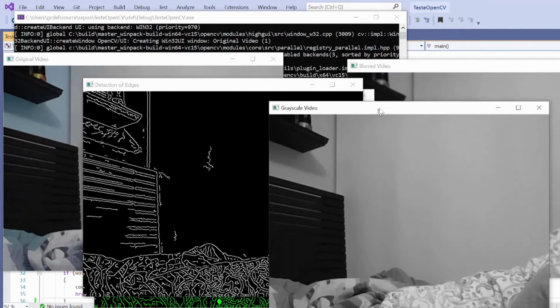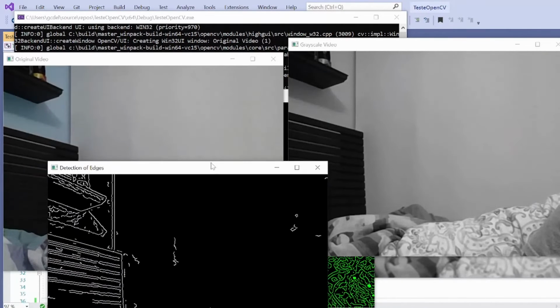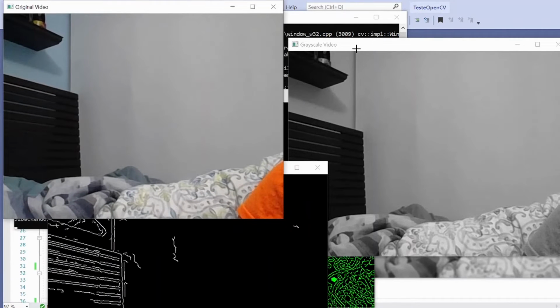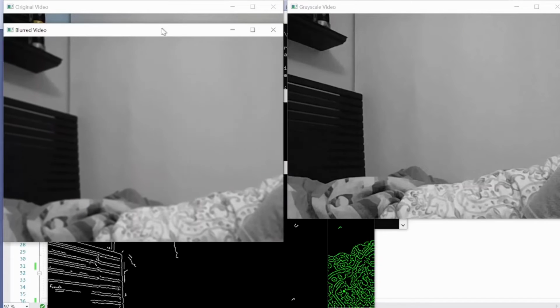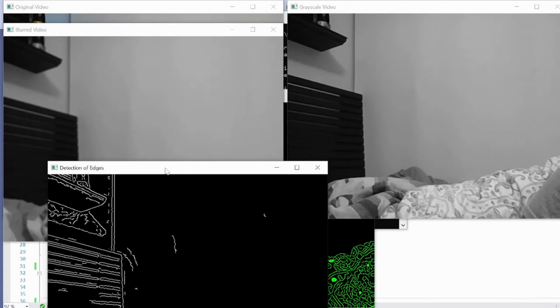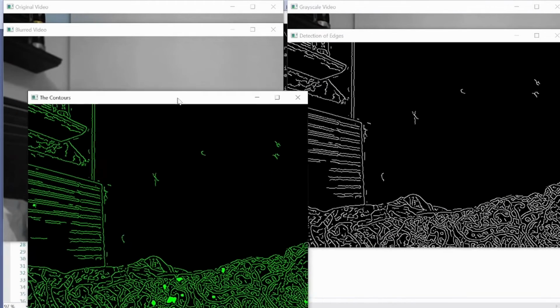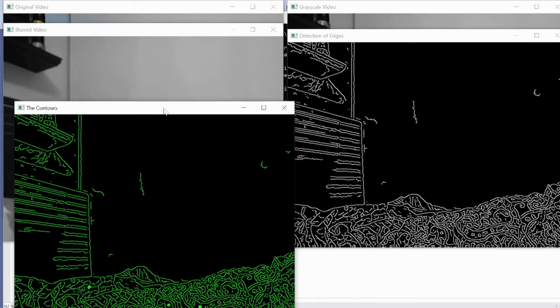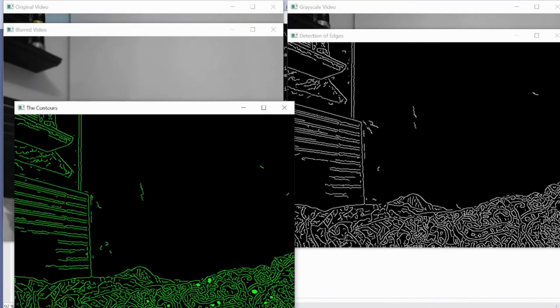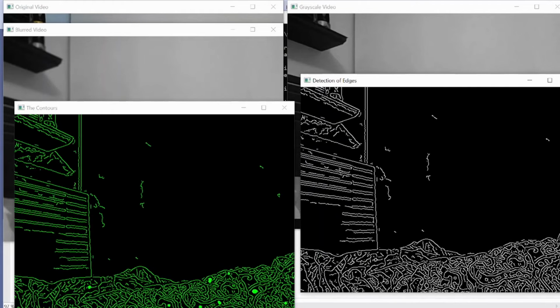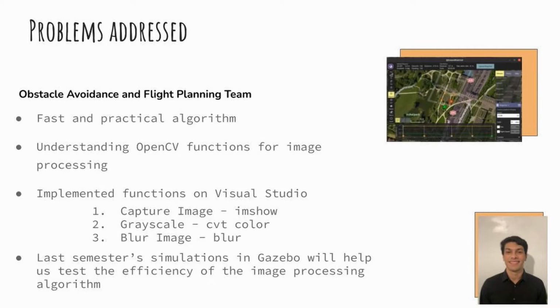The filters used reduce the size of the three-dimensional RGB matrix to a two-dimensional matrix, containing only values of the color gray. After reducing the matrix, other filters were applied in order to identify and draw the edges of the objects that were captured by the camera. This image processing algorithm was originally completed using Windows OS, but at the end of the semester, the team was able to download the OpenCV library in a VirtualBox running Linux and use CMake to build an environment and compile the code in the terminal. This image processing algorithm helped us identify objects to move to free areas.